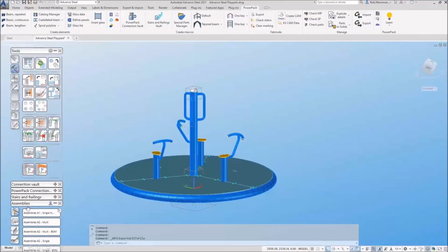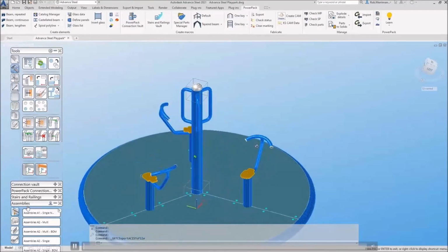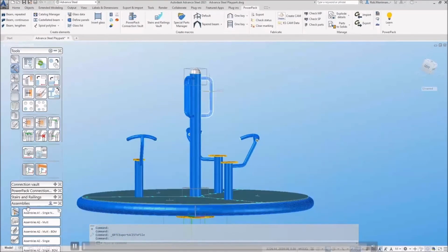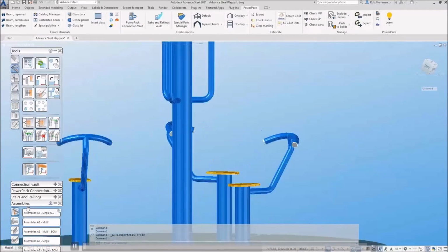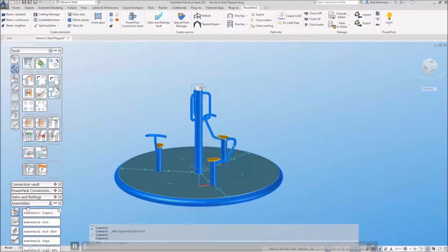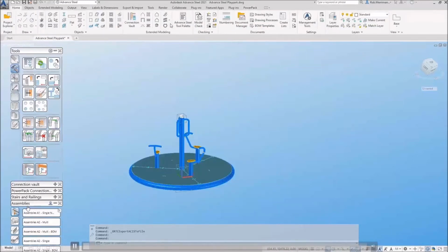Okay, so I have just finished off our little roundabout. I've put the handles on here and then I've rotated the special parts around. The last little bit we're going to look at today is the railing. As shown in the PowerPoint, I want to do railings with no top rail with the hoops on. The out of the box railing macro won't allow you to do that. You need a top rail on there.